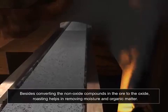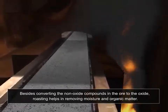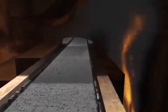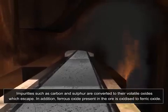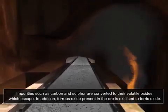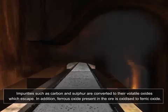Besides converting the non-oxide compounds in the ore to the oxide, roasting helps in removing moisture and organic matter. Impurities such as carbon and sulfur are converted to their volatile oxides which escape. In addition, ferrous oxide present in the ore is oxidized to ferric oxide.